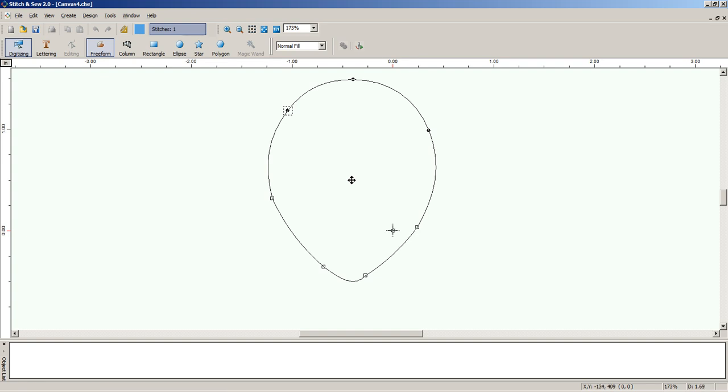To do so, press the Stitch It button here, or right click and choose Enter, and follow the prompts at the bottom of the program. Now it tells you to input the direction. For example, this is setting the angle of the fill. If you want the stitches to run horizontally, click and drag, and you'll notice that a blue line follows your cursor.